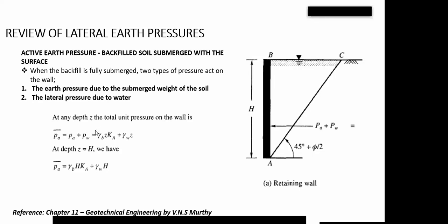So now we've gotten our pressure due to water, and we've gotten our pressure due to the earth material that is submerged. The addition of both of them will give you your resultant active earth pressure at any point. I need to also state, the same way I mentioned earlier, that this small letter pa is dependent on your height. That is, as I'm going down, it's going to keep on increasing. Now, I think this diagram is quite inverted. So in this particular scenario, as you are going up from this sharp point, the horizontal line keeps on increasing.